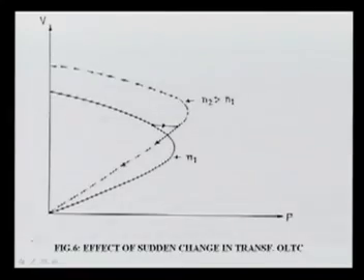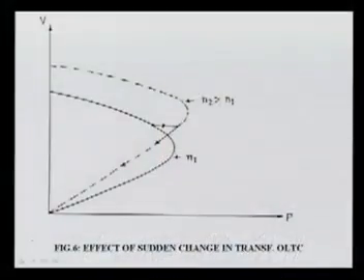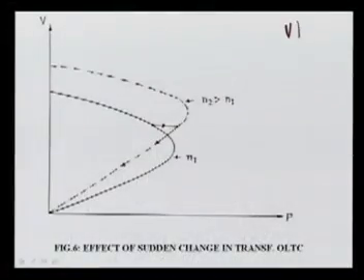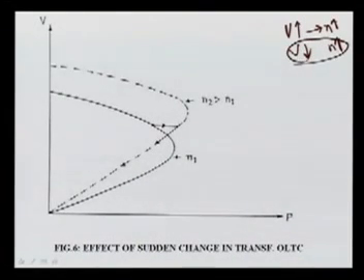Again, sudden change, for example if you want to change in OLTC, as I said, it is online load tap changing transformers. Under loading, there will be some sensor circuit that will try to change the tapping to maintain the voltage. And here, to increase the voltage V, no doubt n must be increased. But in the reverse action of OLTC, if you increase this, the voltage is decreasing, and that we don't want, but the sensor and everything will try to increase, as only the tapping option is there. So here it is one case of the voltage collapse.